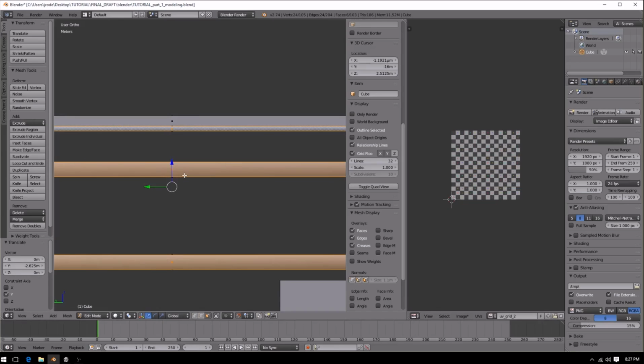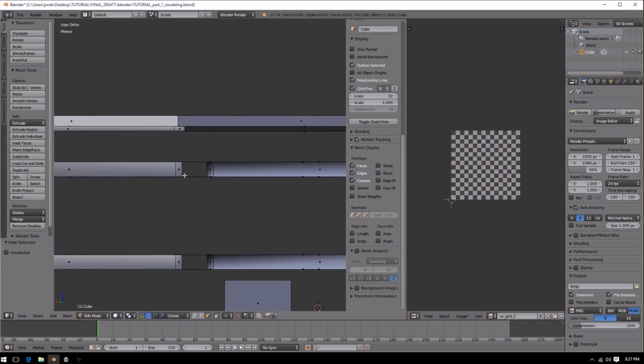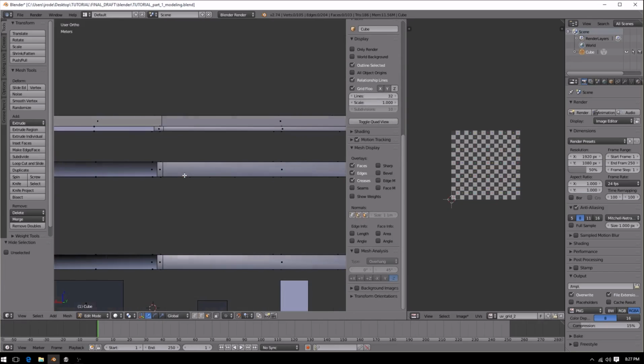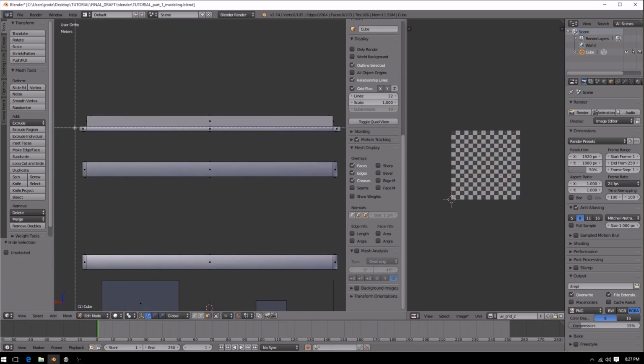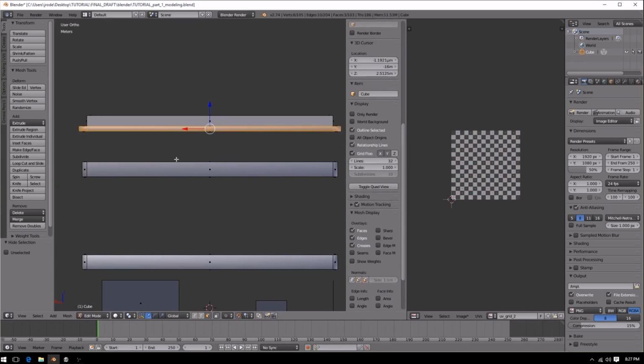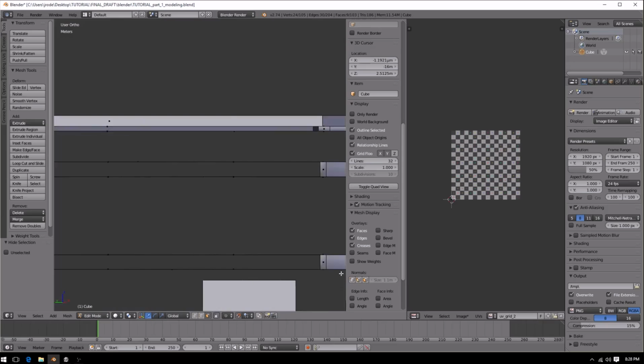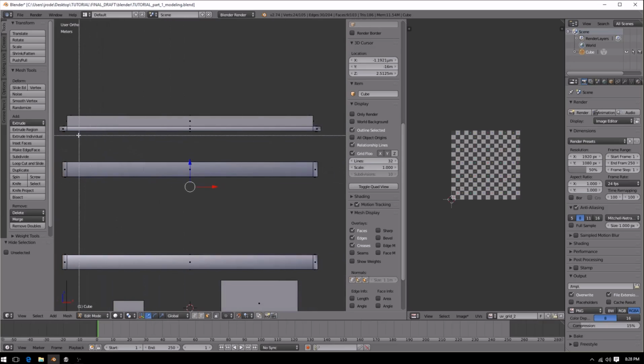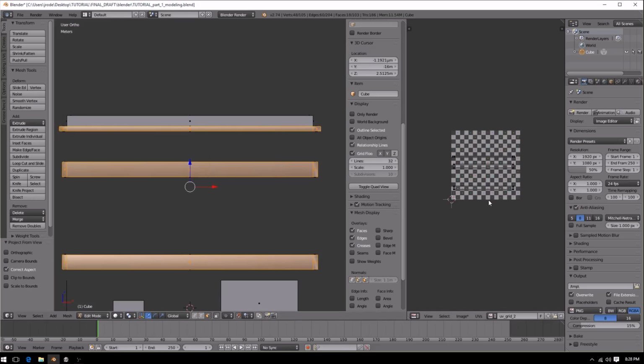And then I'm going to hit H to hide these, and then move around again to the front. And I'm actually going to use B for box select. If you left click and drag, you can now select fronts of these. So I'm going to do it this way. And then use 6 and 4 to pan around and do the same thing for the fronts here. Alright, and then I'm going to hit U and project from view to unwrap. Click A and move all of these down.